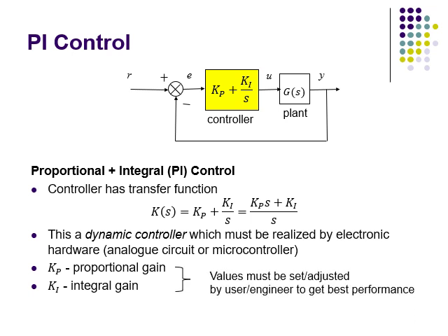And as with the proportional controller, we need to choose or tune the values of the controller gains. But in this case, we've got two gains that we can vary independently. So we can choose Kp, we can choose Ki, and the values should be set in order to get the best performance that we can. But the suitable values for Kp and Ki will depend on the system, so they'll depend on the plant G and the characteristics of the transfer function of the plant.